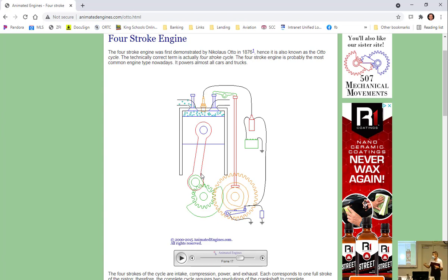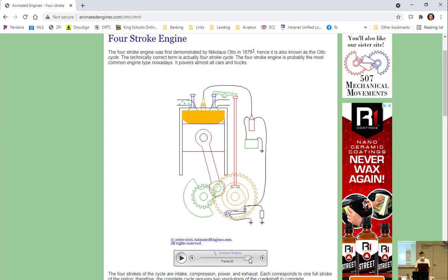Yes, in seconds. So it's a slow burning of the fuel. This slow burning starts, but that piston is moving fast, right? So here it comes. It's coming up. By the time it gets to the top, the fuel has burnt and expanded, and will now start pushing the piston back down. So here we have spark, which is what we're going to talk about. The magneto creates the spark, and it causes the burning, expanding fuel-air mixture to push the piston down.